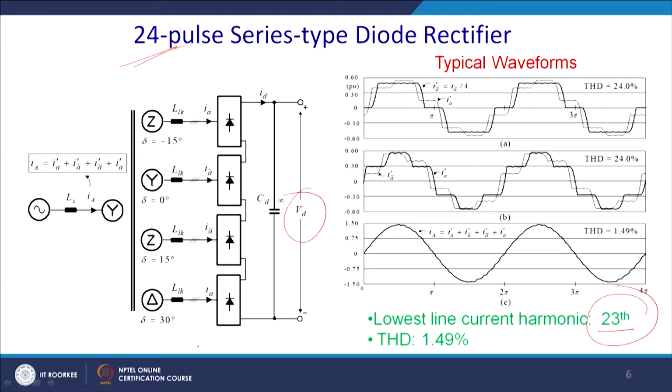You see there is one part of it, this part and this part is nothing but your 12 pulse converter. So, you can have a star with a 0 phase shift, and thereafter with respect to it a 30° phase shift. So, there is a vector group that will operate, it is YD11.